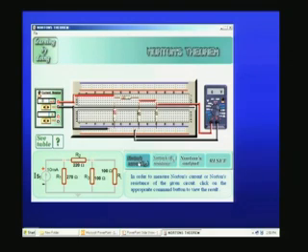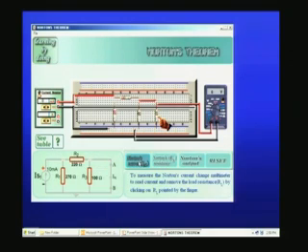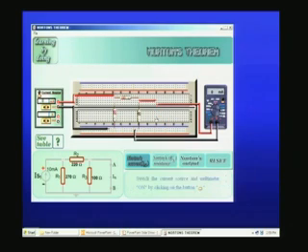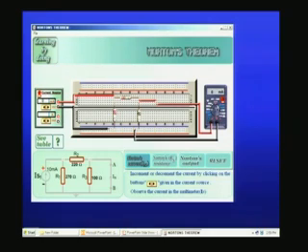Now Norton's current, let us measure. What we have to do? We have to short the load. Therefore we have to remove the load. So go and click here. The load is removed. In place I have got the multimeter in the milliamp range, in the current range, and I have the current source here. Now let us switch on the current source and the multimeter.